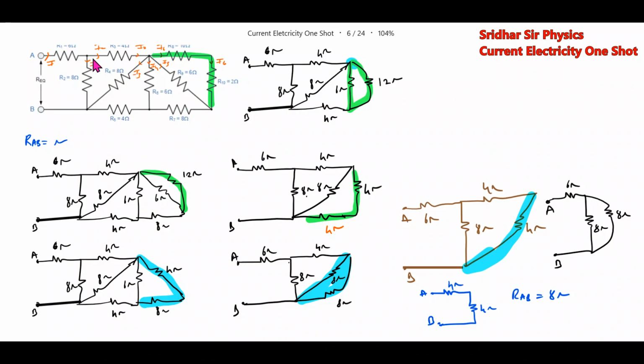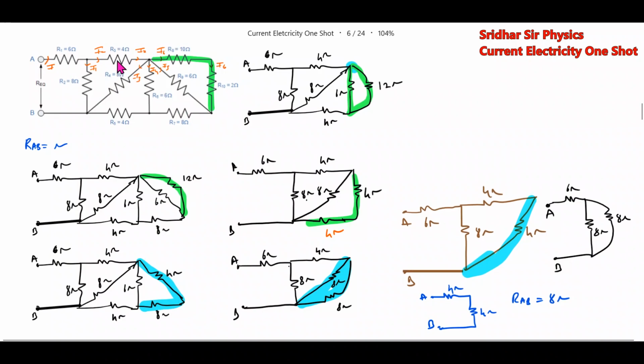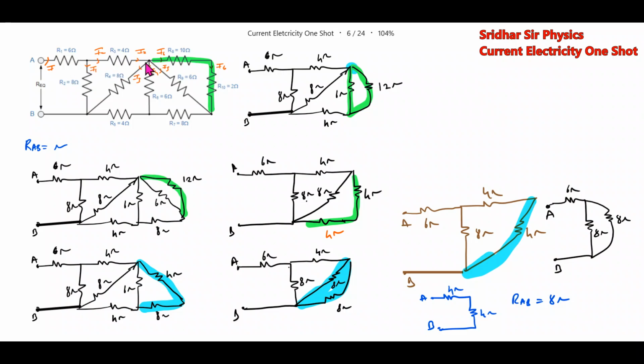Okay, kids. If you have a circuit like this, what you should do is identify the series and parallels. First, branch the current. Where the current remains same, they are in series. Where current branches, they are in parallel. Like this, everywhere the series parallel. With that, you should identify and replace that with an equivalent resistance. So, the resistance across terminals A and B will be 8 ohm.